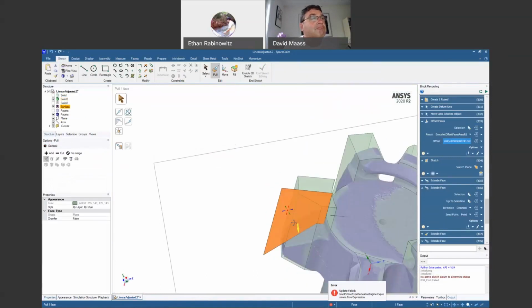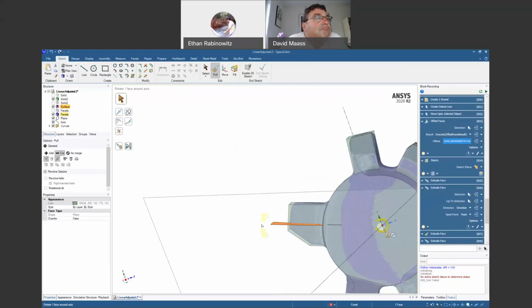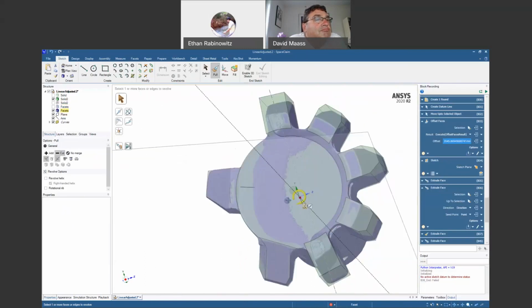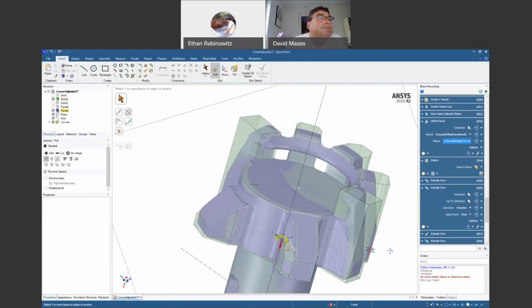Grab that. Alt select our axis. Make sure we're on revolve. Oh, I didn't actually select there. So axis, we'll do a cut. Here we can pull in both sides, so a symmetric pull. And this is one where we should just be able to drag and let go because it's not going to overcut into the cylinder, because it's matched up to that cylinder there. Right. So looks good.